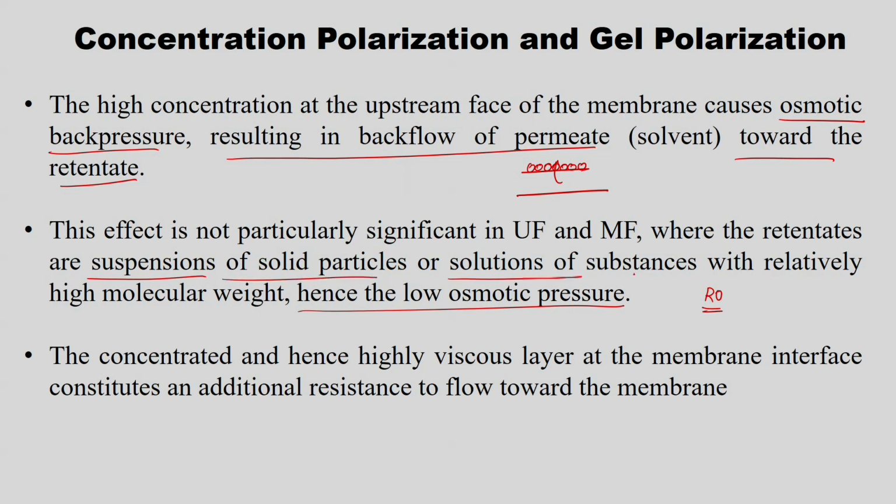solid particles or solutions of substances with relatively high molecular weight solids. So we need only less osmotic pressure. That is not the case with reverse osmosis, where salts have a high osmotic pressure compared to solid particles or high molecular weight components.